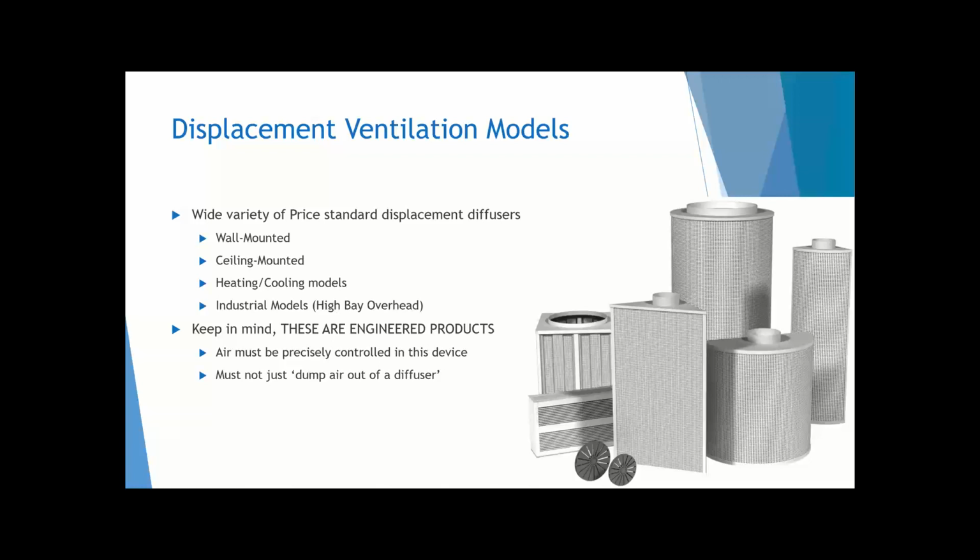So like I said, most of these systems end up becoming custom, but we can provide standard displacement diffusers as well. All types. We have wall mounted, ceiling mounted, heating and cooling models, industrial models. And keep in mind, these are engineered products, right? It's not just a diffuser dumping air into the space. This air must be precisely controlled. There's baffles behind this that must slow down the air significantly and really provide that air at a calculated rate.